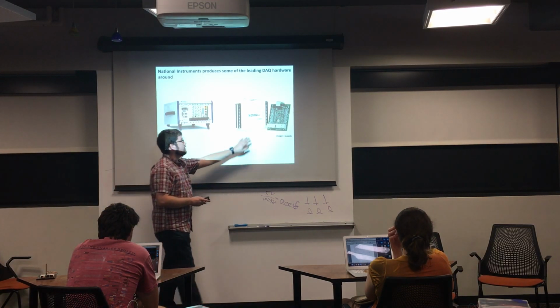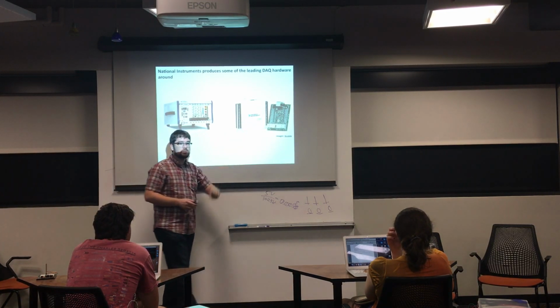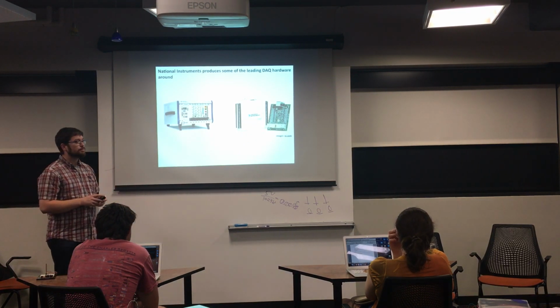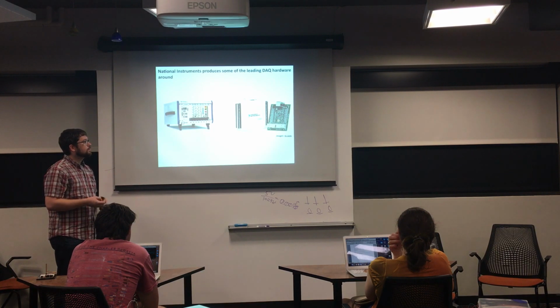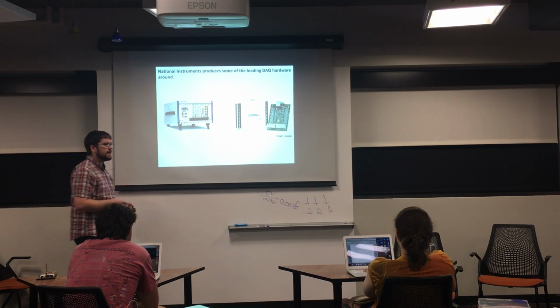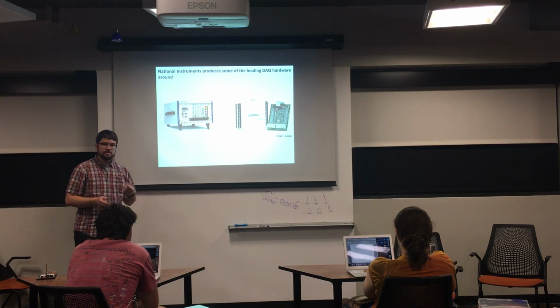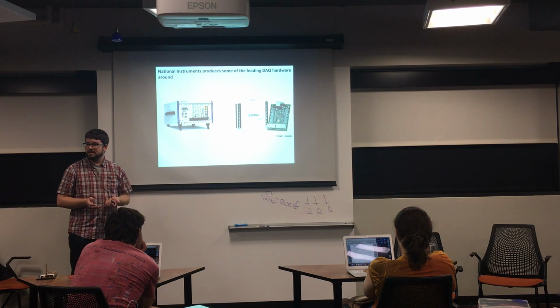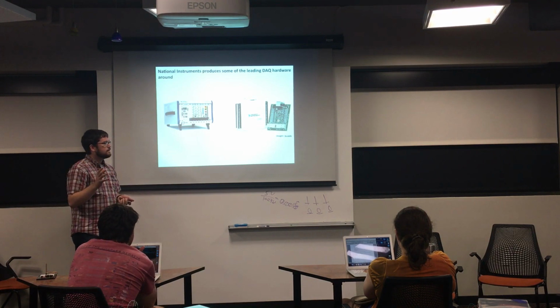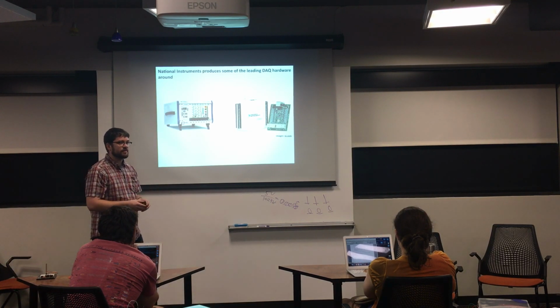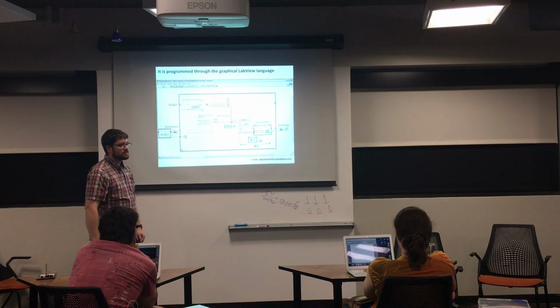And they also have these little small modules that just plug into the USB port of your computer. They're not as fast, they're generally not quite as accurate, but they're pretty good. You can look on eBay for a thing called MyDAQ, M-Y-D-A-Q, that they came out with as an educational product a few years ago. You generally pick them up for around $150. You've got a 16-bit, several channel analog to digital converter, digital to analog converter, all kinds of stuff in it. Plugs right into your computer. It's pretty handy to have in your desk and in your toolkit.